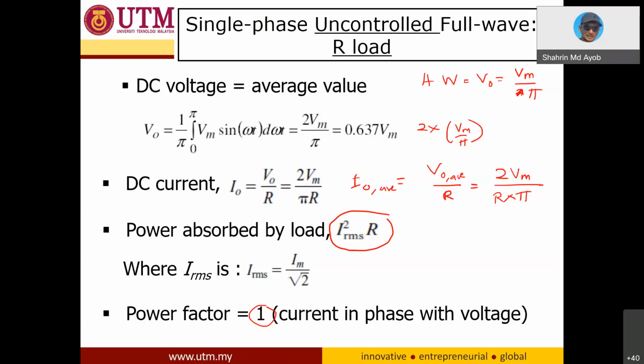Okay, so if you are given a choice of which one you want to use for rectification, please use full wave rectifiers instead of the half wave. Okay, because it doesn't distort the power quality at the input side.